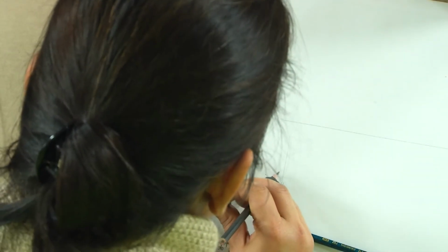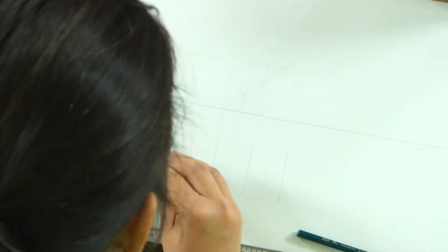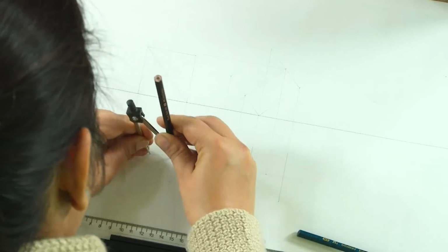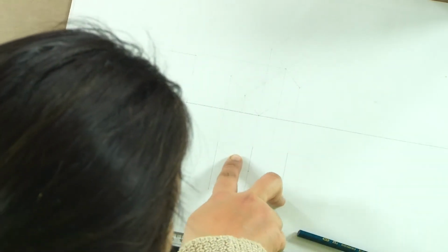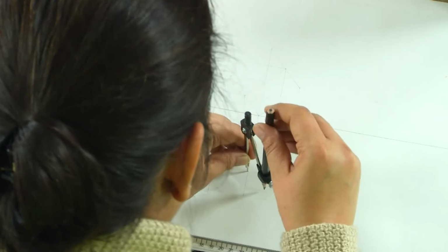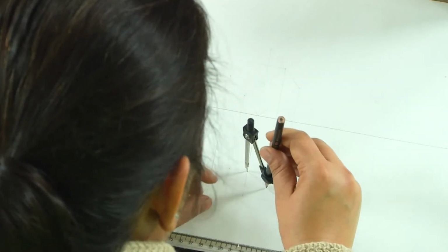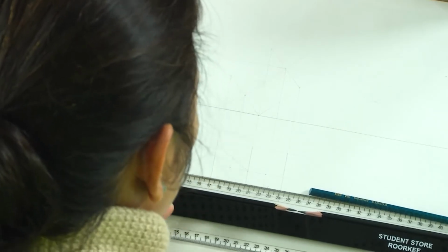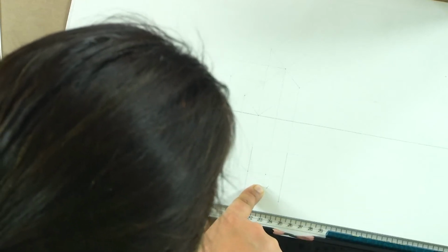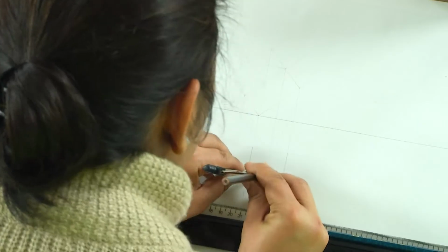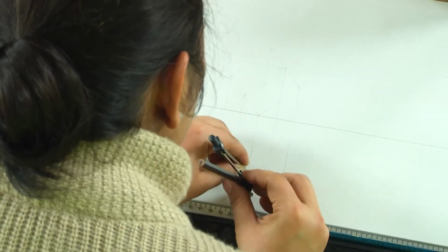So the original axis, which was originally parallel, is now inclined at 30 degrees, and we will have a line passing through this, and the trace of this will be taken onto this line passing through the 30-degree point, which is exactly what we had done earlier.